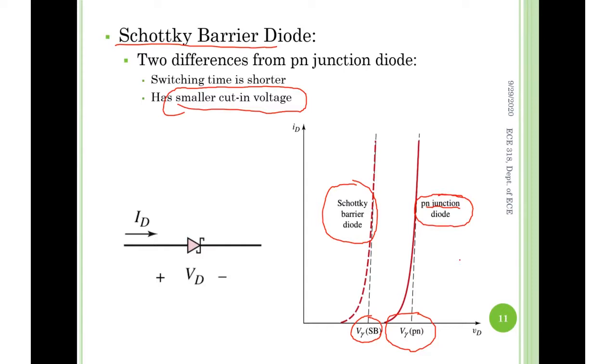Use p-n junction? Yeah. And first of all, in a low voltage application, why do you prefer the Schottky? If you had some application where you wouldn't get up to the cut-in voltage of say 0.7 volts or something of that sort, you would want to use the smaller diode. You know what I mean? Yeah, I do. That's basically close, and Shane's concern is basically close.